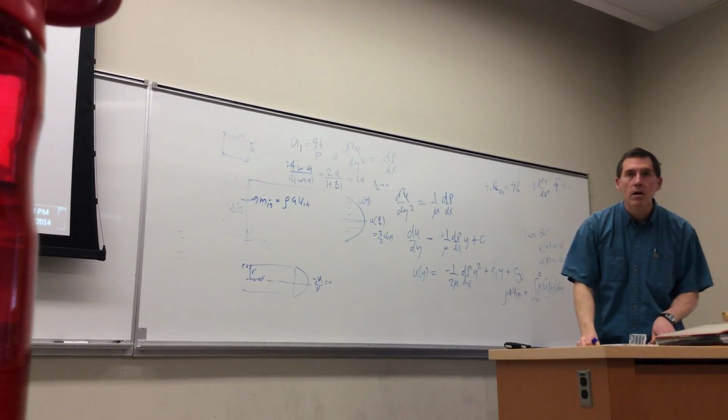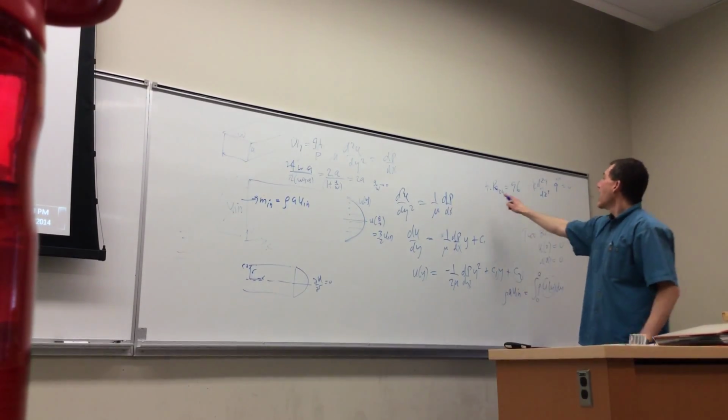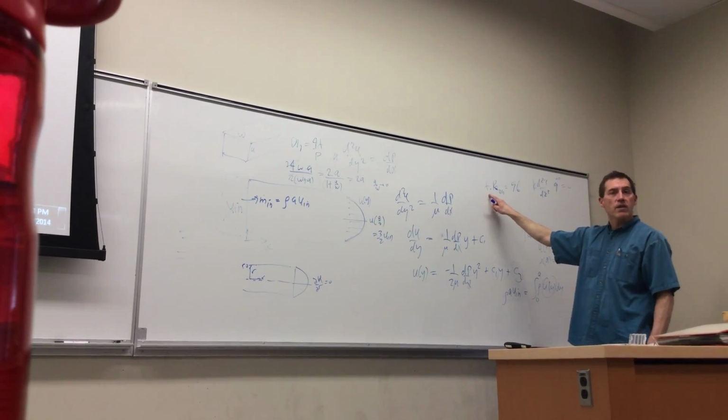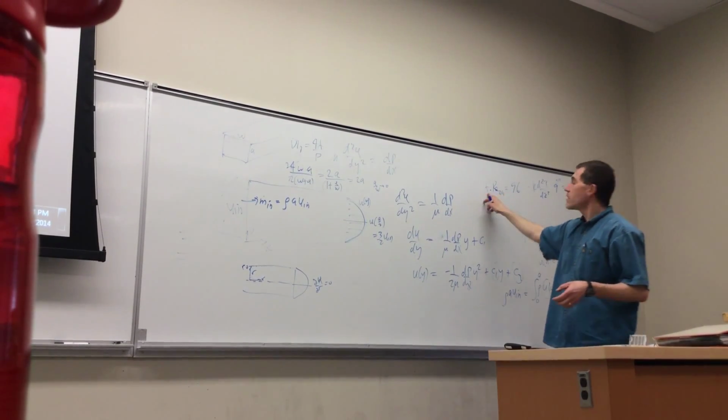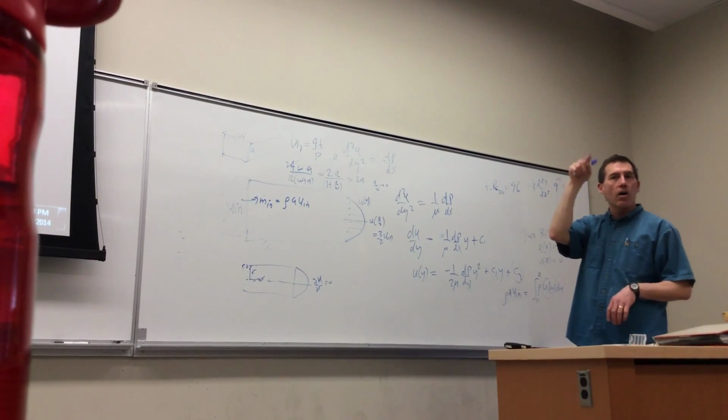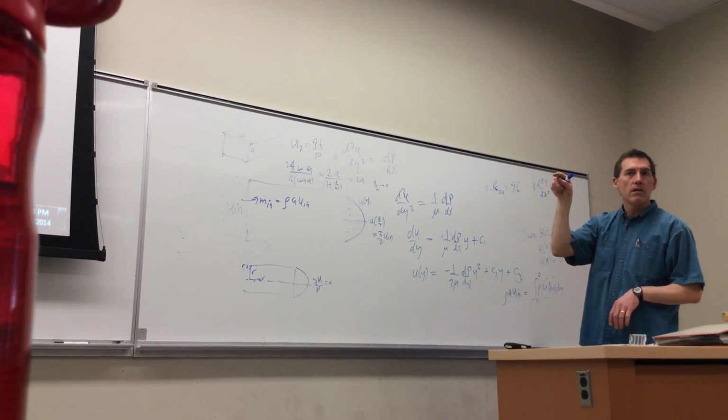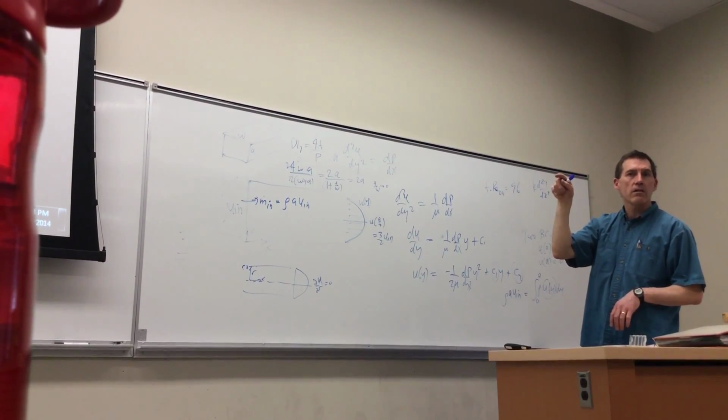They want us to derive that? Yeah, well, okay. And how would you derive that? If you take the definition of this, which is likely tau wall over half rho u n squared, the friction factor.